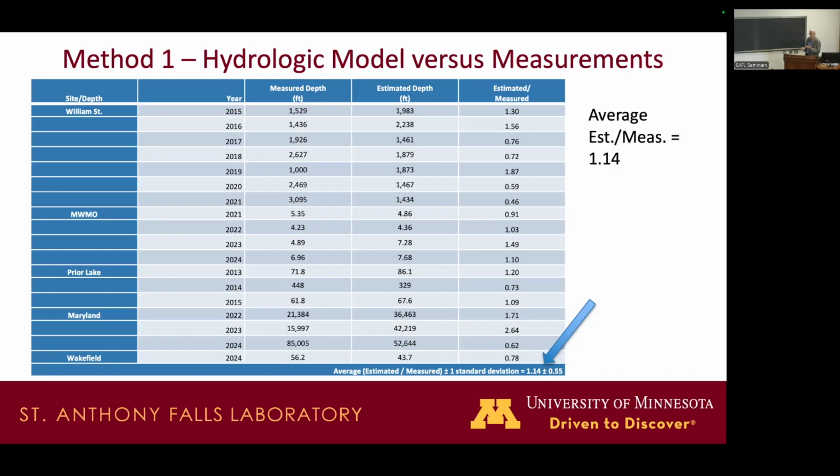Anyway, in a stormwater system, it's fine in a stream where you always have water, in a lake or something like that. Well, probably in a lake, but in a stream or whatever where you always have water, it's fine because you always have 4 inches of water. But in a stormwater system, you don't always have 4 inches of water. A lot of the water comes through at less than 2 inches, and you are not measuring that at all. Okay, let's move on.